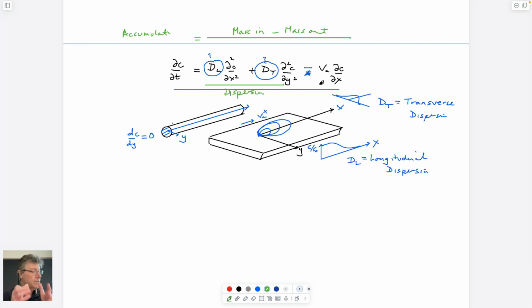And this is advection, physically being carried with the water, just like you're doing in assignment number 4, which is this mass flux here, which is advection. We made the comment that these dispersions are kind of pseudo-diffusions, and we use Fick's law. And they're kind of pseudo-diffusions because we represent them by a dispersion coefficient, which includes something that relates, so let's do that as